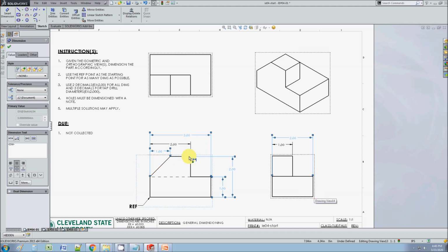Okay, so then they're going to keep going up until 2. So I'm trying to figure out how they're going to machine that. So they're going to take their end mill, go all the way to 2. Alright, and down to 1. So they're going to use that value again. They're going to take their end mill in this direction now up until 1, and then shave off the back from the center line until it's flat. So as you can see, I did not have to select anything more than once, and I did not have any dimension that was not selected. So I selected everything exactly once, meaning I do not have any missing dimension, and I do not have any duplicate dimension. Okay, if I had a missing dimension, it means I would have been stuck.